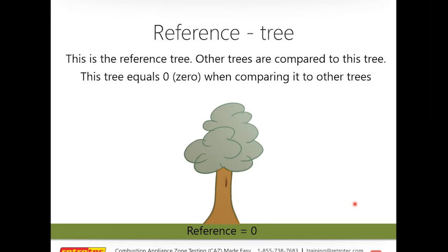And that's really important when we talk about how we test and why it's important to pay so much attention to the details as we go through it. So I want to give you an idea of what we're talking about when we talk about differential pressure. In a differential pressure, you're always going to have a reference and your input. The input will always give you information with reference to something. That reference will always be 0 when we're talking in numbers.